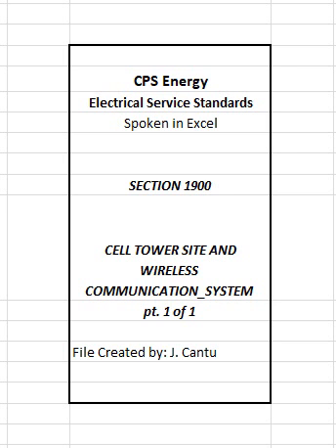D. Underground service on customer meter pedestal. Service and metering equipment shall be designed to be installed on a pre-approved customer meter pedestal along with necessary communications equipment. Customer meter pedestal shall be located at an approved location on customer property or a pre-approved location on public right-of-way, refer to Figures 1902 and 1906. Note: Customer shall be responsible for furnishing and installing meter pedestal but must select one that has been pre-approved by CPS Energy.